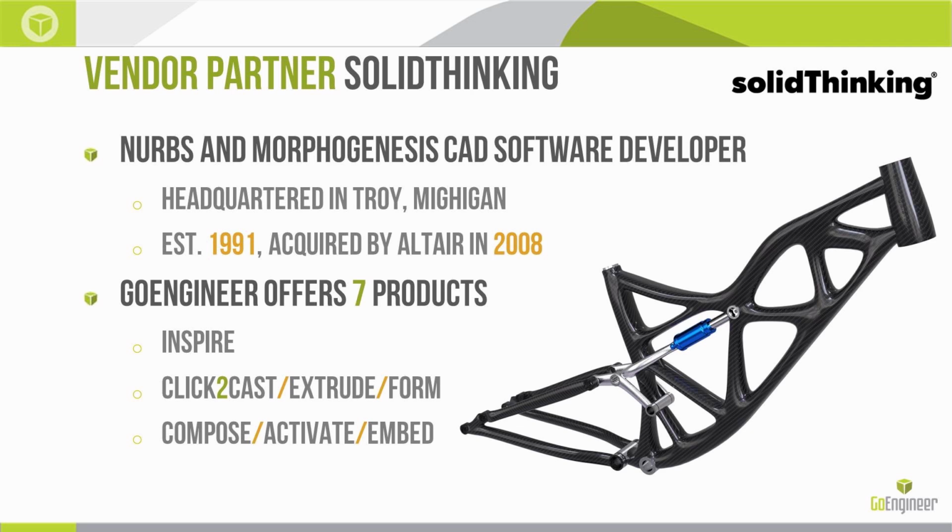The biggest difference with designing with topology optimization is that the engineer or the designer, instead of taking their best guess at a shape and then simulating afterwards and refining through that process, they simply define boundary conditions, mainly a working envelope, load cases, and then they let the tool whittle down the shape based on the critical geometry that's needed and the working envelope.